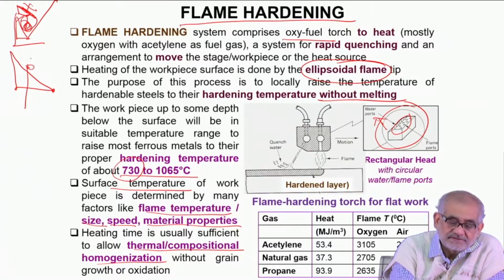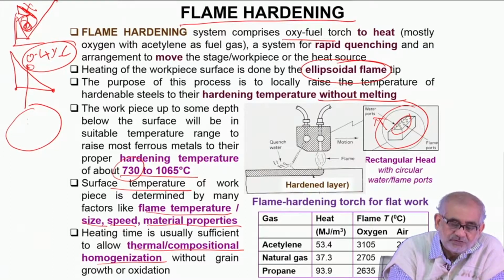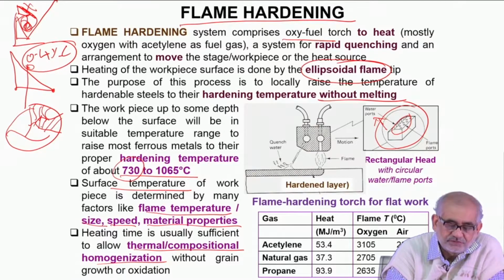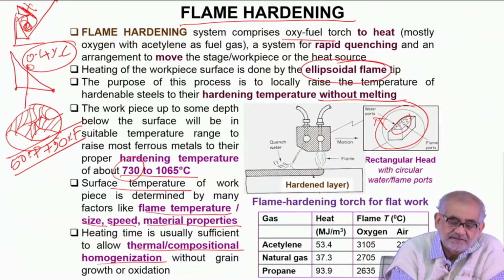Now, we are talking about, let's say, 0.4% carbon steel. So if we are talking about 0.4% carbon, at room temperature, we expect a 0.4% carbon steel, typically a mild steel, should have a microstructure which will be both pearlite and some amount of ferrite. So we'll have pearlitic zones and maybe some ferritic regions left in between. So typically we expect sort of 50% pearlite and 50% ferrite. This is the kind of microstructural aggregate that we expect from a 0.4% carbon steel at room temperature.